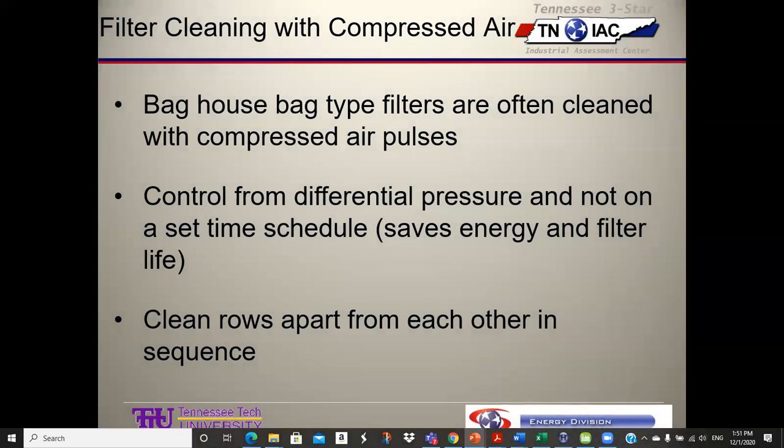Filter cleaning with compressed air, a bag house. A bag house has filters in it called bags, often cleaned with compressed air pulses. And so what happens is maybe you have dust being generated in a process, and so you have a fan that is outside blowing or sucking this dust-laden or dirt-laden air through this bag house, and the bag house is full of these bags, and the fan moves the air through, and the air and the particulates hit the outside of the bag.